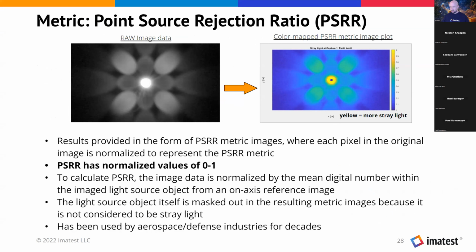But there's no further calculations like luminance and so on? So there are other metrics out there. If you want to do the bookkeeping of measuring the illuminance or irradiance at the location of the camera, you can and you should do that. There are some metrics like the flare attenuation metric in the upcoming IEEE P2020 standard that do utilize radiometric measurements like illuminance to normalize the data. Okay, thank you.